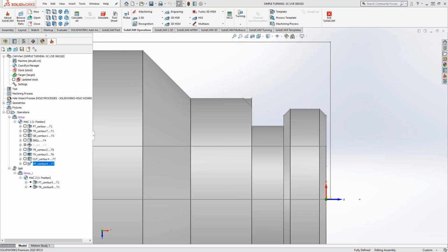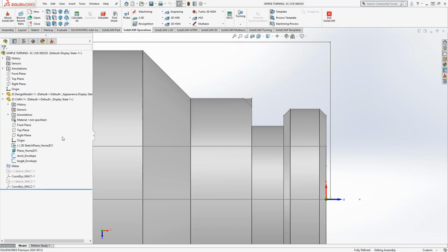And while you're trying to find that, I've got a question from Brian. What is the difference between a sketch in CAM and a sketch outside at the assembly level? So here's the difference, or at least the way I like to put it: if you do a sketch at the assembly level, it would actually populate down at the bottom where it says coordinate system, yep, down there. What that would do is if our model was to change, that sketch would still stay there. So if we're doing a family of parts and you still want to keep those sketches, that sketch would still stay. If you did a sketch inside of the design model area, then when we go to do our change model reference and change that out, that sketch is gone.